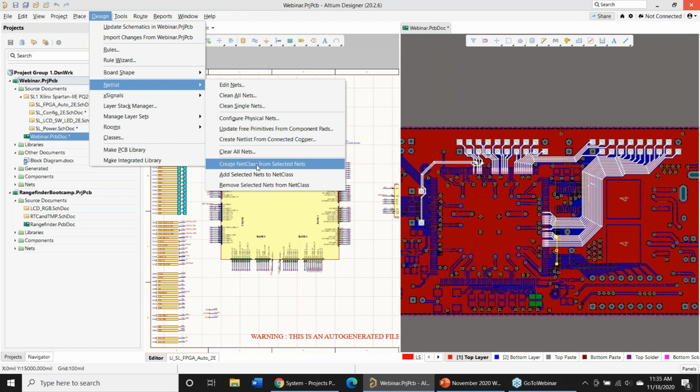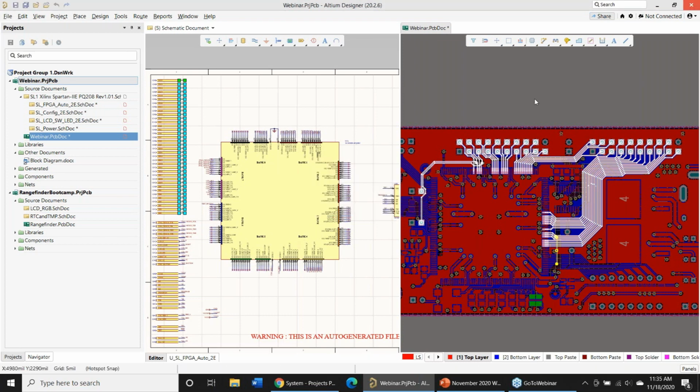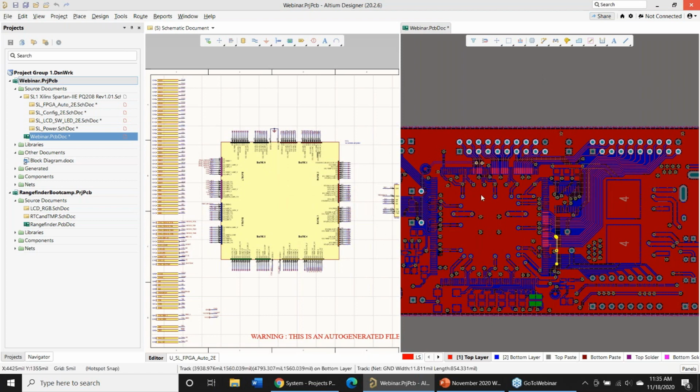I wish they would just use that. If you did exactly what I did with the components, those three bars with the arrow does not light up. For some reason, Altium hasn't brought that in there yet. But I can add this net class and call it HA and HB nets. Okay, and I'll come back to those later when we look at something else. So I say okay, and now I've got a net class here. Very nice way to use cross selection to be able to look at two different designs.